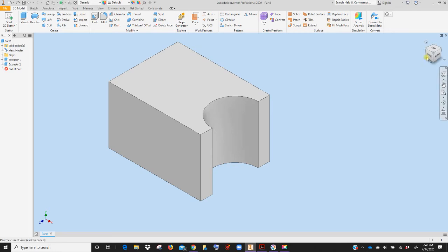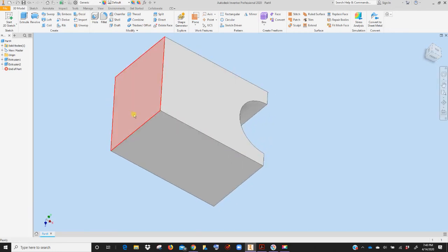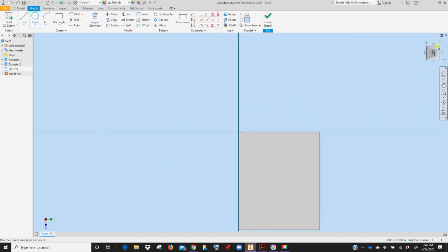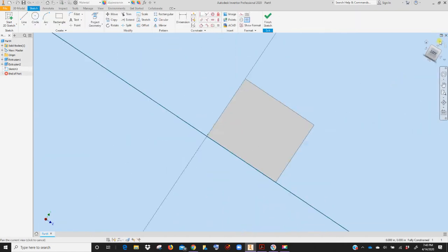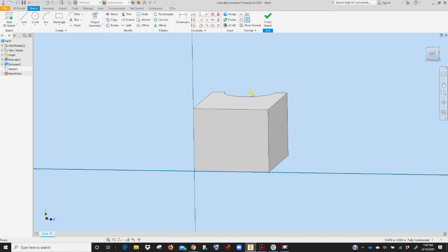We've got a 2-inch radius on this back corner pulled forward. So I'm going to sketch on this back face. Now let's flip this over, because it put me in a weird position, right? This is where I want to be, and it's okay to move this. Yep, see, there's my circle back there, so I want to be on this back corner.